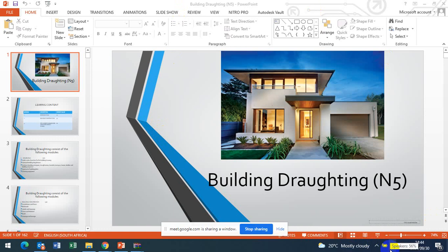So do not draw a floor plan on a site plan because it's got its own question. Students are usually getting confused about the dimensions that are given on a site plan for the house. Is it the internal dimensions or external dimensions? Please, it's external dimensions. Those dimensions include brick thicknesses and everything is in there. It's your floor area. You can't go more than that.